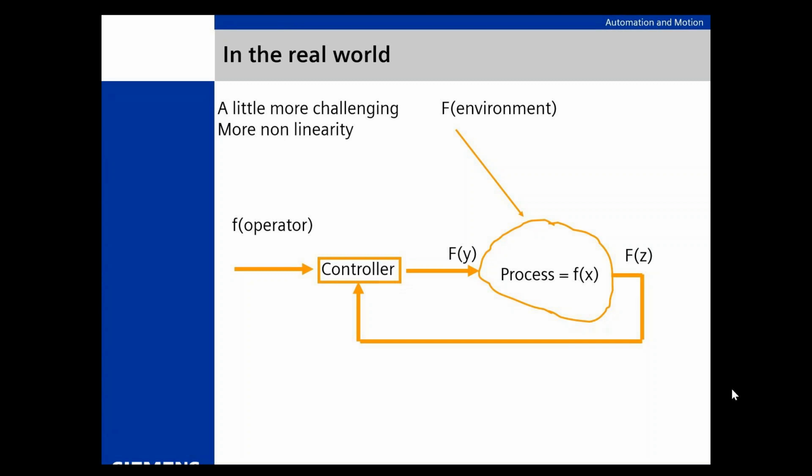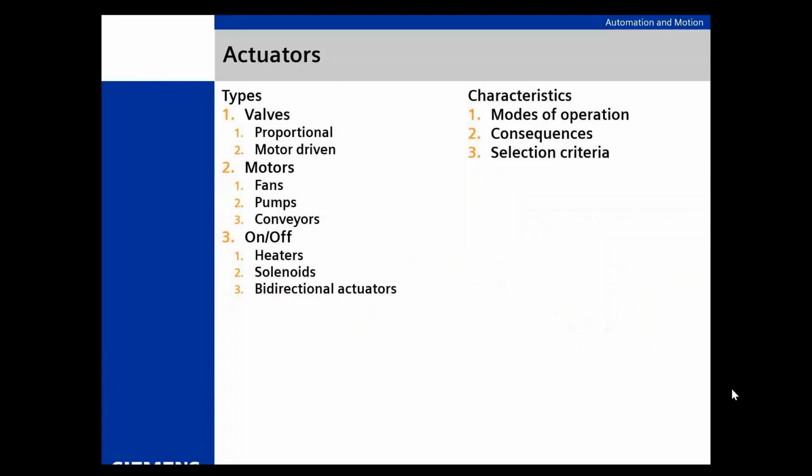All right. What we call actuators, which is a word we use in the control world, is what I'm doing. The controller itself, be it a single loop controller or a card in a DCS or some sort of software laying on top of a PLC, is doing something. It's telling something to do something. It's turning a motor on and off. It's turning a fan on and off.